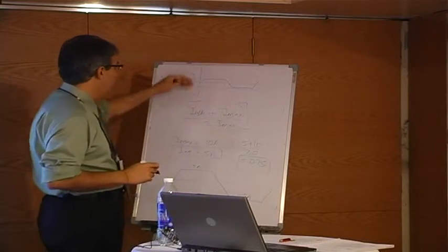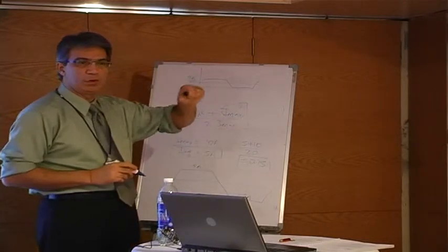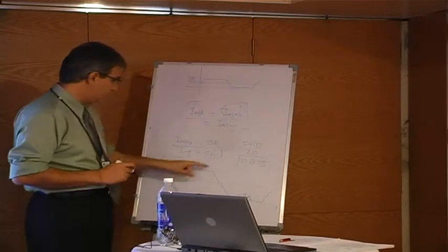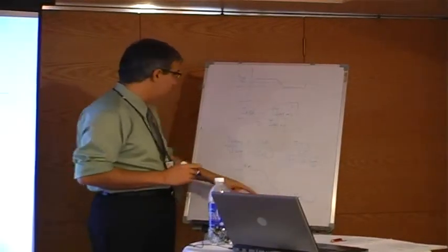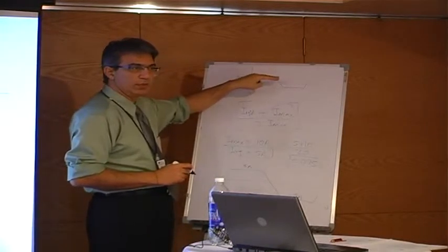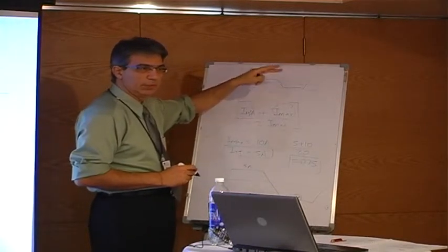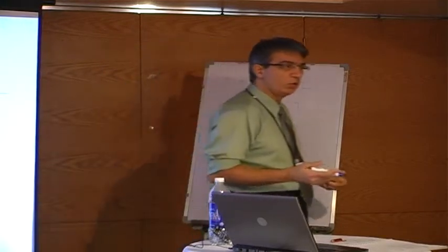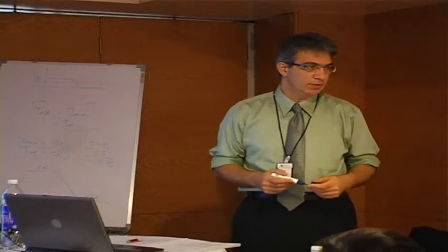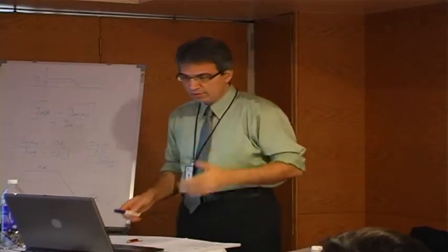Okay, so it's shifted because our PWM will only take duty cycle values from 0 to 1. So we take this current from 5 to minus 5 amps, shift it by the maximum current, and then feed it to the duty cycle DA. You have to do that anyhow if you're using a DSP because you can't handle negative currents at all. So it's a level shifting you're doing.